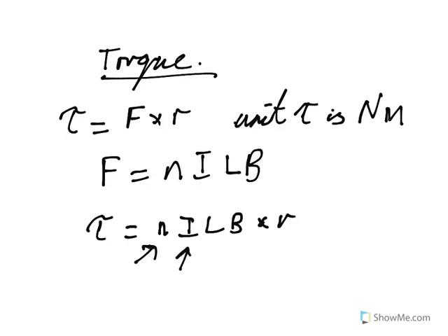The current, you can increase the current flowing through it, and then there may be limitations to that within certain applications. What else can you do? Well, you can increase the length of the coil or the wire in the magnetic field. Again, there may be certain limitations, and we can increase the permanent magnetic field. Again, in certain applications, there may be